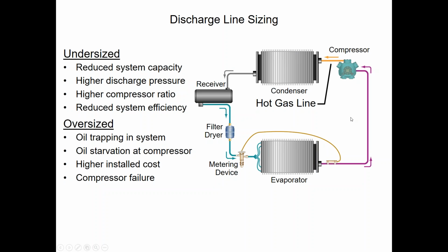So the refrigerant vapor can always entrain the oil, and of course the liquid can too. It's just that the vapor state lines have a little bit harder time entraining oil, so it's a slower entrainment that occurs, unless of course we flood back. If we're bringing liquid back, so something's wrong with the system or metering device or what have you, low load, we start bringing liquid back.